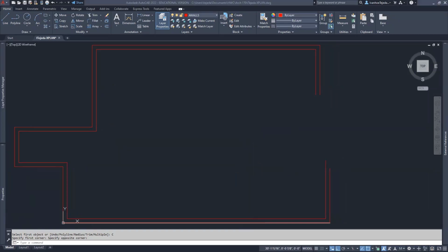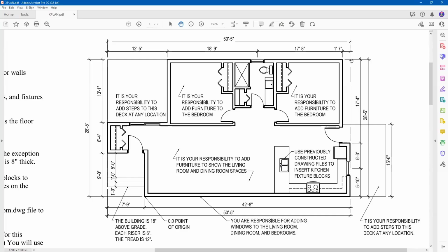Now it's looking right. And it looks like it's going to come down a distance of 17 feet, 4 inches. I could measure from the bottom here on up, but those are two dimensions that I would rather not have to figure out, since I already have the one above giving me an overall distance there that I need.